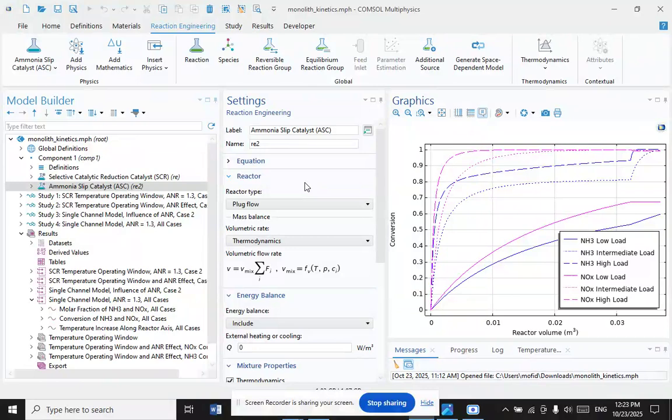Single channel model to find the lowest level of NH3 required to reduce the NOx present in the exhaust gas. A reactor model accounting for changing reactants, compositions, and system temperature is needed. From a mass transfer point of view, channels of the reactor monolith can be considered to be uncoupled to one another.